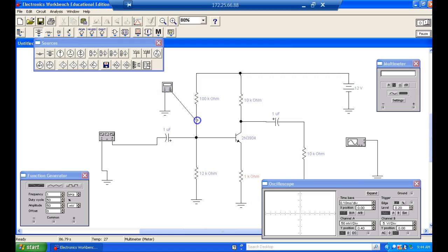And we hadn't looked at the AC signal. So here's our base voltage. It's going to go up a little bit, but not very much, because we anticipated that, right? We ignore that resistor over there anyway when we calculate that. We will get some voltage right here, but it's going to be just coupling through that diode through my load.